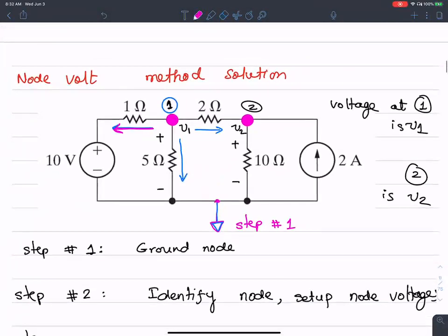This current is not branching into two different paths. There's only really one way for it to go. For my analysis, if the current has only one path to follow, then I'm not going to consider that a node. Even if I did, it's not a big deal. All I'm going to get is, let me call this I total and this I1. According to KCL, I'll end up with I total equals I1. It's a trivial equation. Okay, perfect. Thank you. That's a good question.